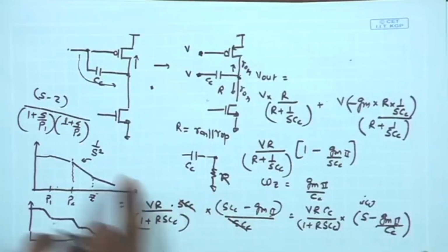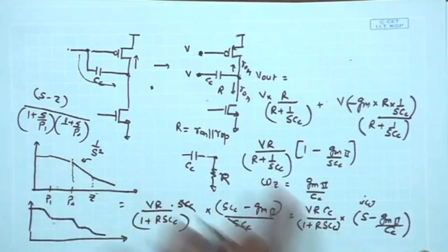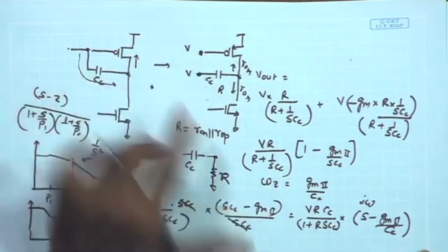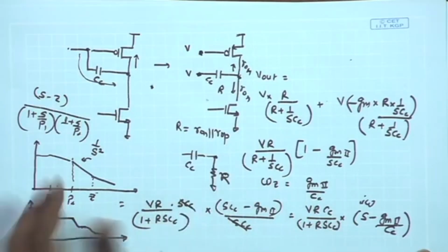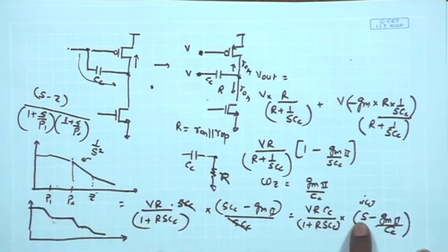At a frequency very greater than that, the phase difference should become plus 90 degree now. No, so here you have the minus sign also incorporated. So, if you look at the previous stage, you have a negative sign coming because of the previous stage and you are having the iota omega coming over here.